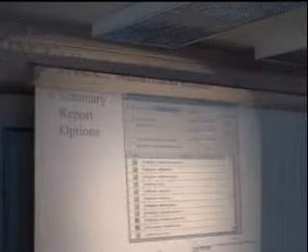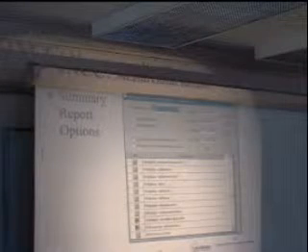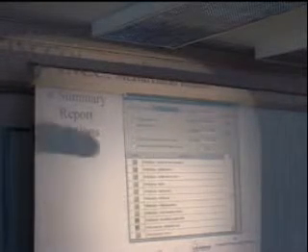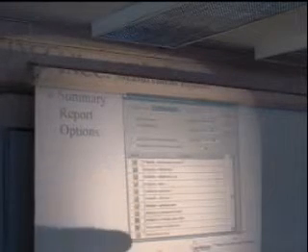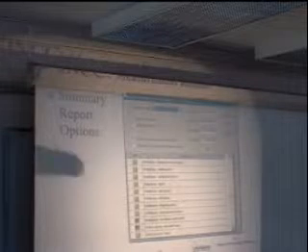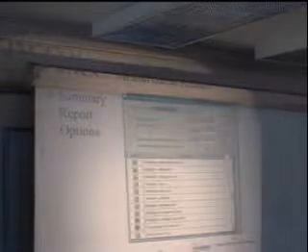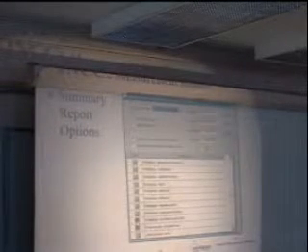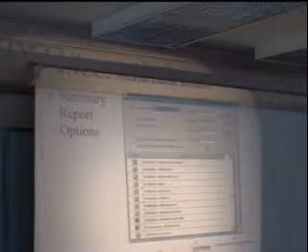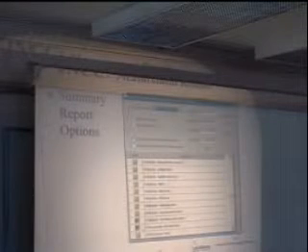You just pick a range of measurements to look at, and then there's a huge list of things here, all kinds of parameters. You have to scroll down and pick the ones that you want. The heading that's displayed there, for example, the one that's checked says multiplicity, pre-delay, and gate width. That's what shows up in the header of the comma delimited file. So when you pull it into Excel, that's what you see.